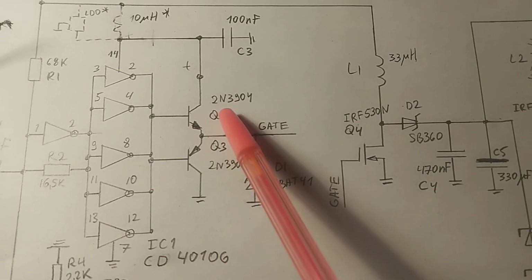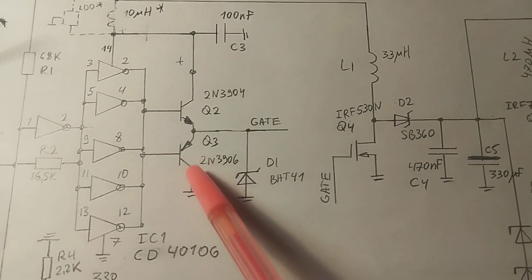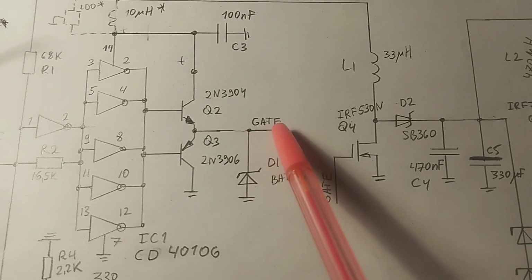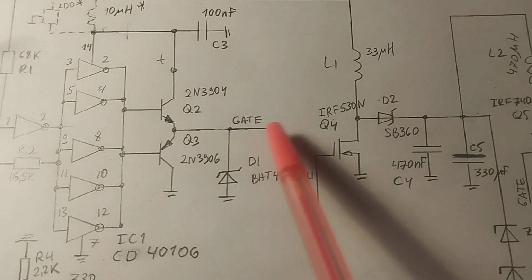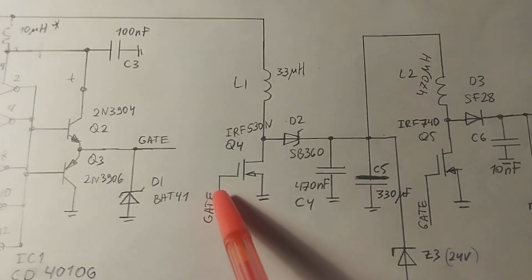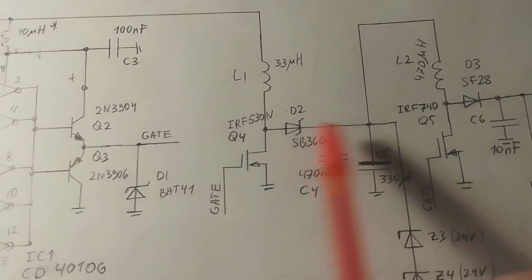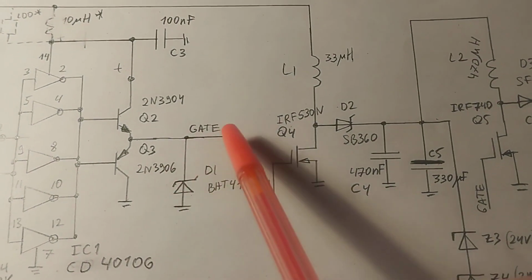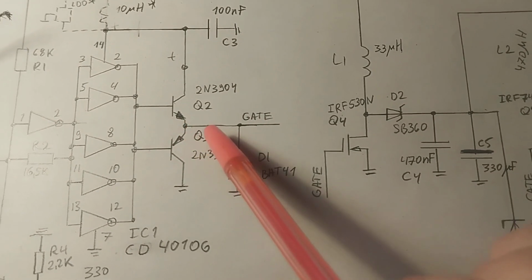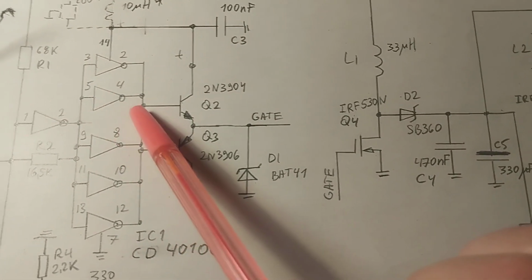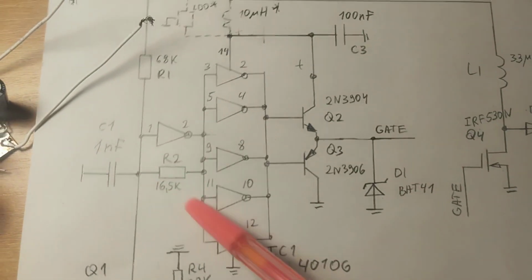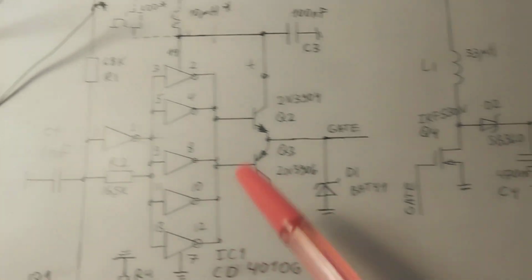So I use 2 transistors, 2 emitter followers, to amplify the output current. To reduce negative spikes from the gates of the first and the second stages I use Schottky diodes, because negative spikes may cause incorrect work of this schematic.